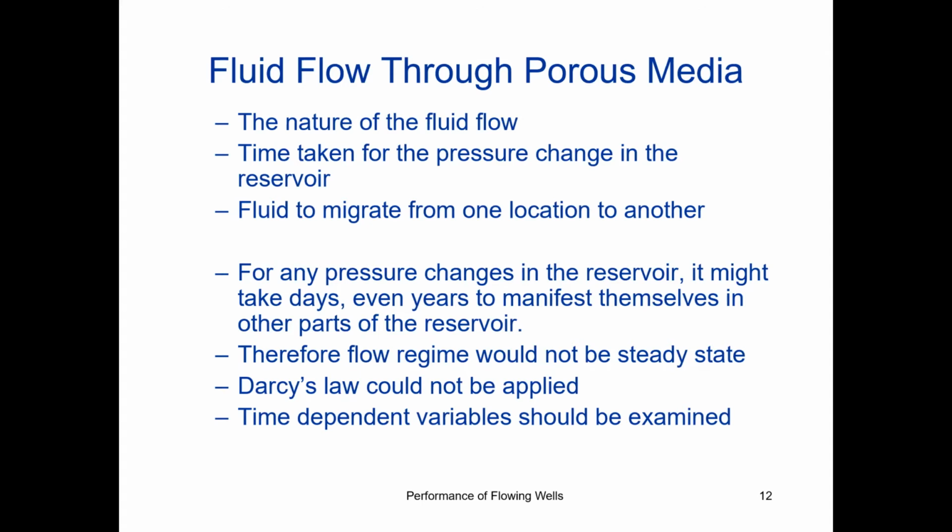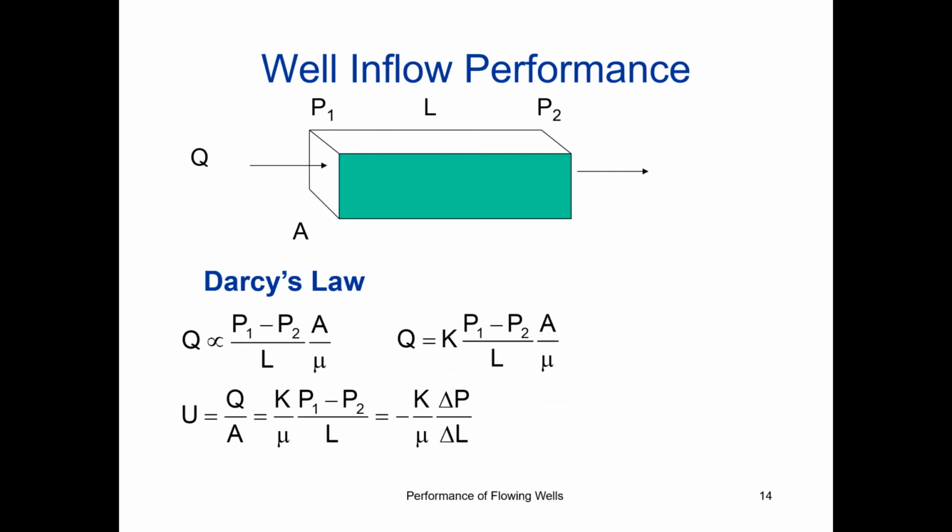So if you have flow in the porous media, that is the flow in the reservoir, then it has some rules and regulations. We use a modified version of Darcy's law, because Darcy's law is designed for one fluid and isotropic flow. But the principle is correct, and we use it as much as we can.